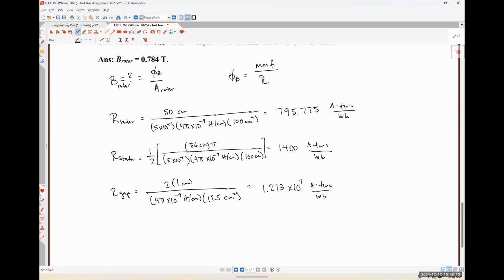But that concept of energizing coils in a fixed pattern is a very common way to use motors. Your DC brushless motors work in a very similar way. You have a whole bunch of coils in your stator, typically 6, that you can energize at particular times using what's called an electronic speed controller, which is just a set of transistors timed in a particular way.